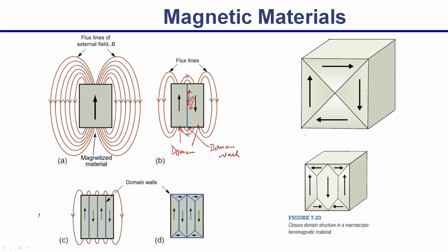And as you know, that is talking about spins, but in a particular grain, as we talked about, you can have many thousands of electrons present in a material. Now, depending on the alignment of the spins, you can have domains, and these domains will be separated by domain walls. As you can see here, this is all taken from Michael Aspie's books on nanomaterials and nanotechnologies. The spins can be aligned in a particular way, and then switching of the spins is possible from one domain to another domain, and that is how we can explain the domain formation in a magnetic material and how these domains can lead to magnetization.